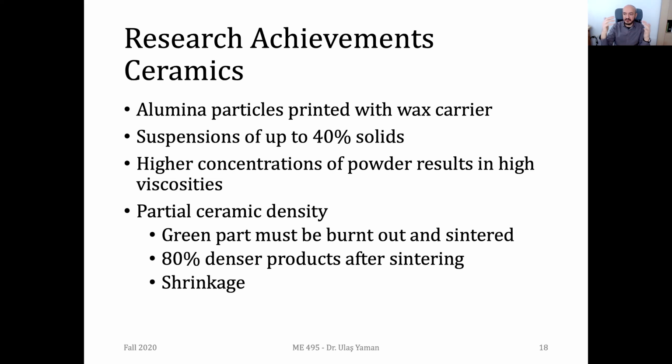Yes, depending on the complexity of the shape, as your friend pointed out, we need to use support structures as we have seen in the video. Since we don't have a kind of bed for material jetting, we need to have support structures. But for binder jetting, we don't need supports, especially for polymers, since the fabrication is done inside a bed. And on the material jetting side, we need to use support structures.